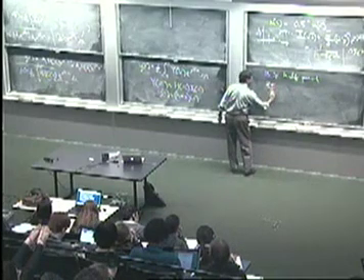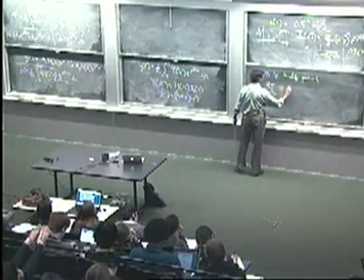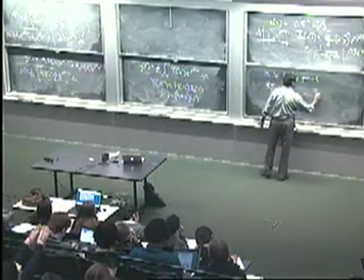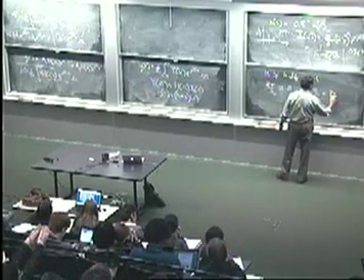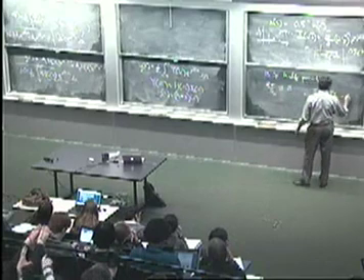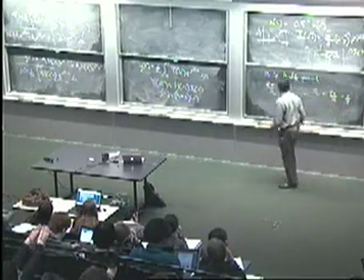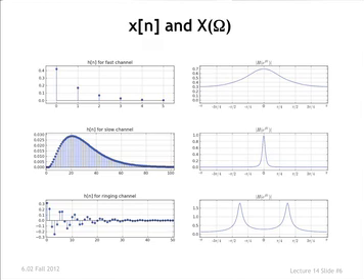Period is 2 pi over omega naught, so I'm saying that's approximately 18. So the frequency that I expect to see, the fastest frequency there, is 2 pi over 18, or pi over 9. Is that roughly consistent with what we're seeing there? Does the spectral content drop off? Well, here's pi over 4, here's pi over 8. Somewhere around pi over 9, we've run out of underlying components, right? It's because the frequency content is limited to that range that the associated signal doesn't wiggle any faster than this. All right?